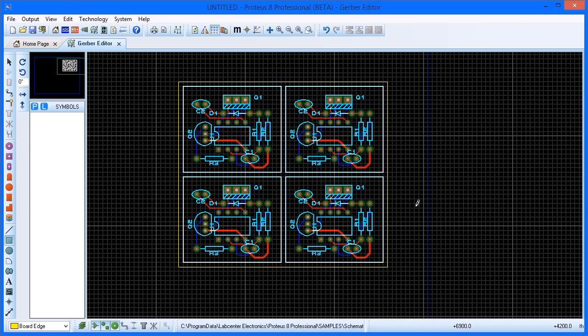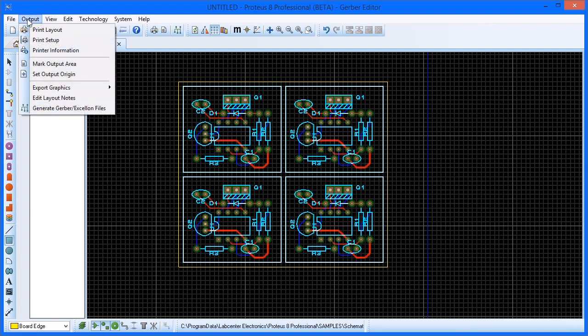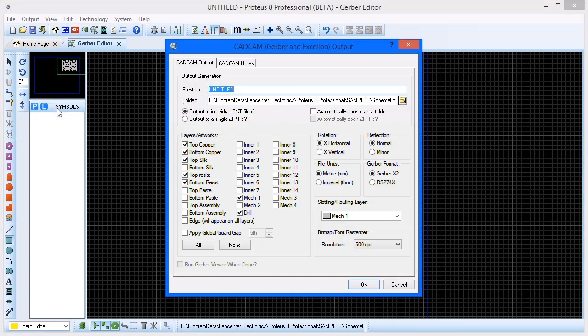Once completed, you need to generate a final Gerber file for the manufacturer. You do this in the same way as earlier and name the work as suits your own requirements. It should be noted that you can add text and graphics to your panel as required in order to give your board an ID and manufacturing information.